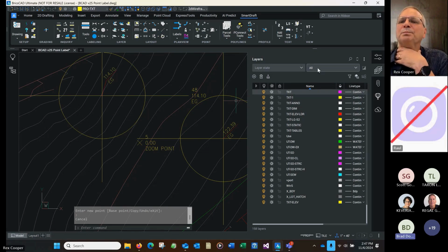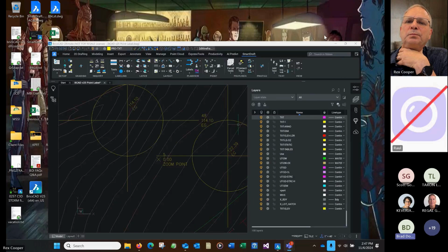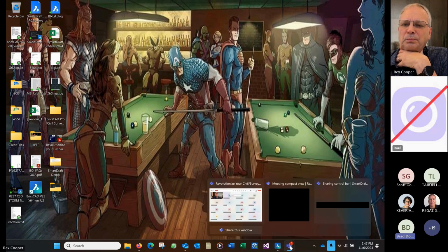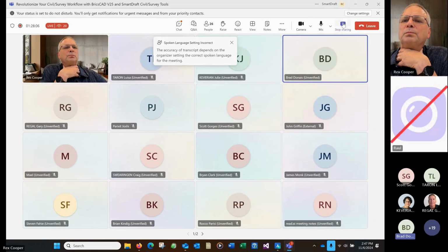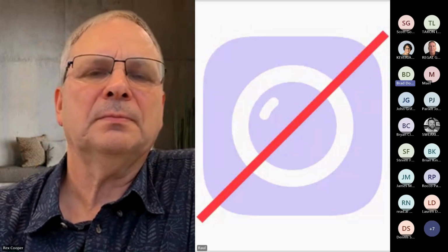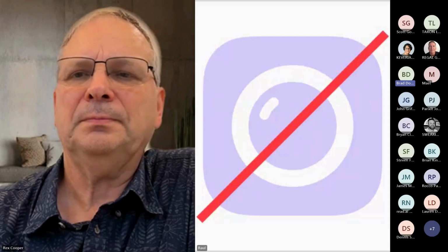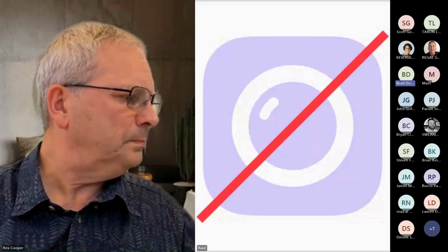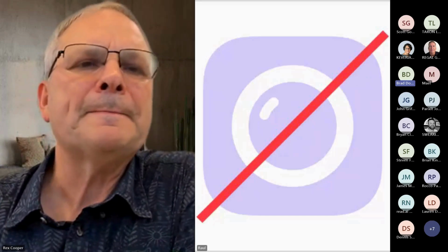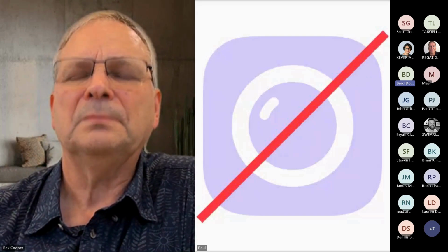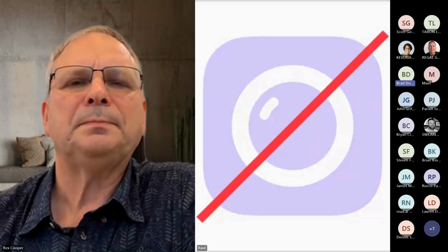Yeah, so at least from a design perspective, you can take any of those surfaces, if you're trying to pull off a top of curb elevation that you don't have an exact shot on, but you've got a good surface built, you'd be able to at least pull fairly closely what that elevation is, at least for some preliminary design purposes. So I use that tool fairly often when I'm doing grading plans or even roadway plans to pick out, if I didn't get an exact survey shot, an interpolation between a couple points where an endpoint might be. So from a design perspective.